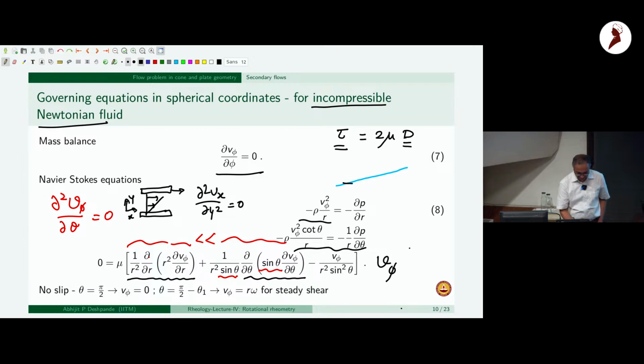Each concentric ring of material has a simple shear flow, like that between two parallel plates. What I mean is one particular concentric ring is moving at omega r, and below it the velocity is 0. You go further down, and again it's basically parallel plate flow effectively. Since the gap is also changing and the velocity is increasing, effectively we have constant strain rate throughout the geometry.